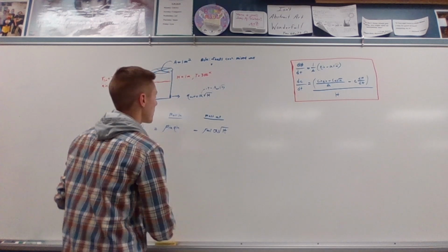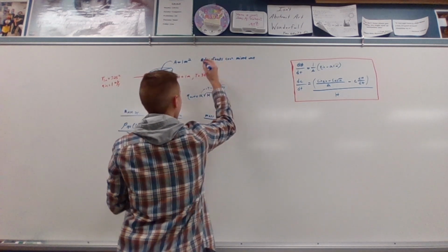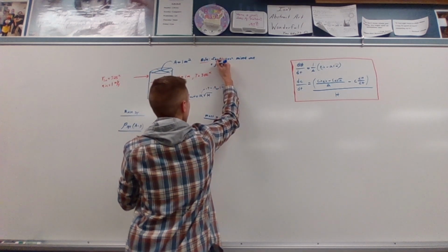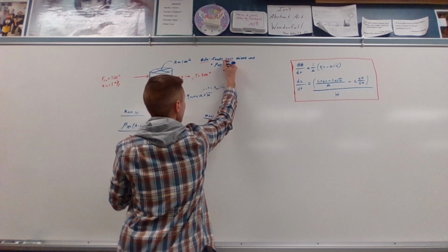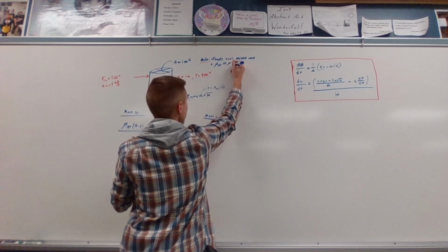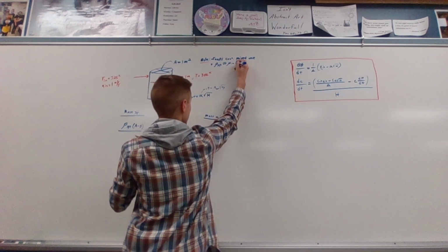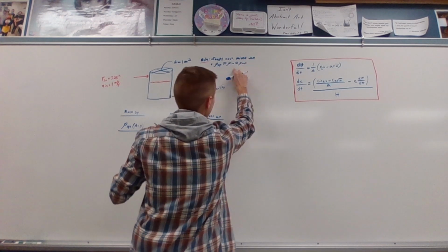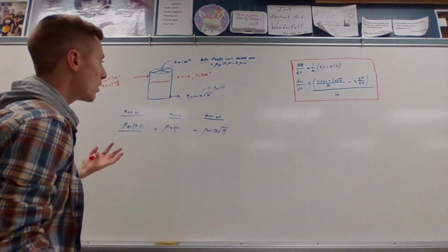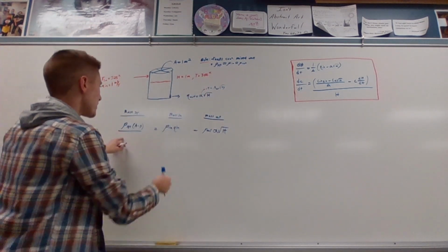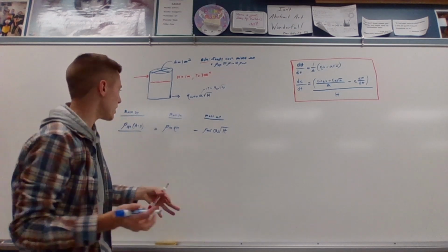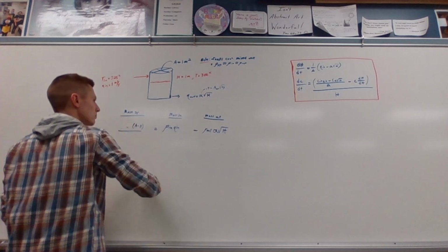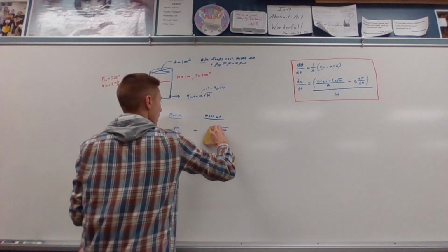So let's go ahead and write that in our notes section. The density of the system is approximately equal to the density coming in, which is approximately equal to the density leaving. So now we know that relationship, we can say that these are all the same value. So if every term has a density, we can go ahead and cancel it out. Okay? So we can cancel this out here and here.